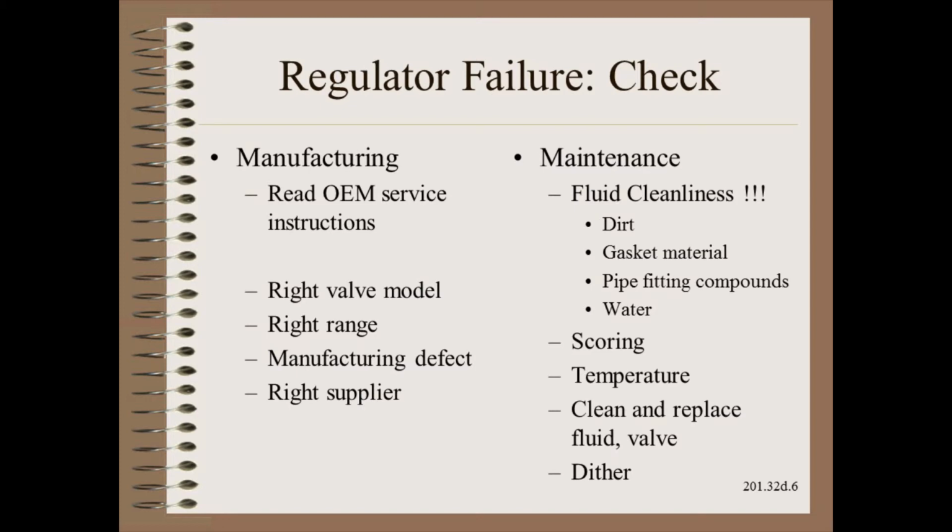Common sources of trouble relate to fluid cleanliness. Even the smallest particles can cause valves to not move smoothly. Flush lines, clean everything up and retest. Finally, some valves have the ability to dither, meaning they shake the valve to reduce friction. Adjusting the frequency and magnitude of dither might help the valve break loose from modest sources of stiction.